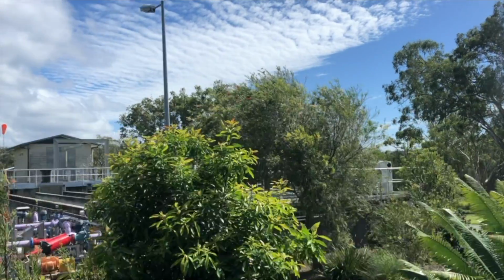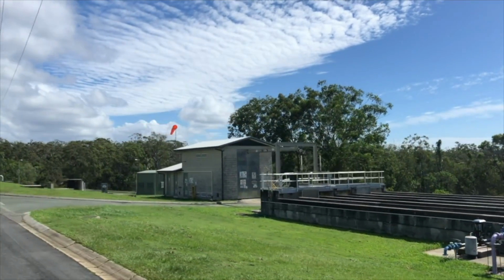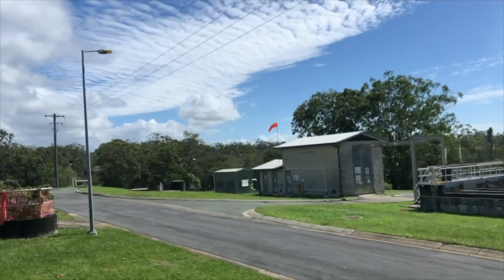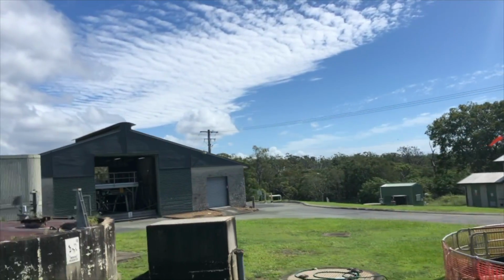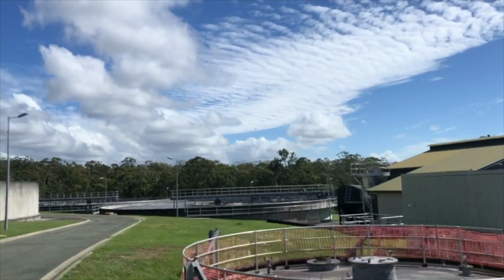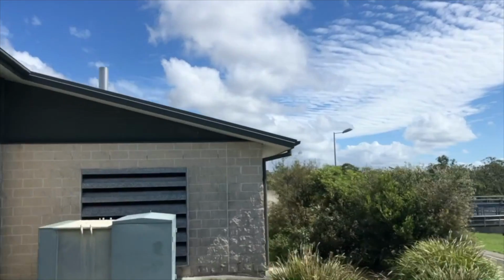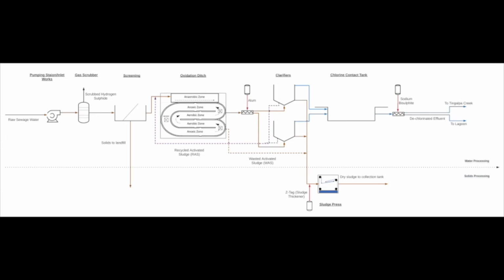Cleveland Wastewater Treatment Facility runs 24 hours a day, 7 days a week with capabilities of capacity control, as most of the machinery comes in pairs that can be tweaked according to demand. The discharged treated wastewater complies with a site discharge permit, which is in line with the Environmental Protection Act of 1994. The Cleveland Wastewater Treatment Plant uses a modified activated sludge process for cleaning the wastewater to dischargeable quality, and the process is represented on this process flow diagram.